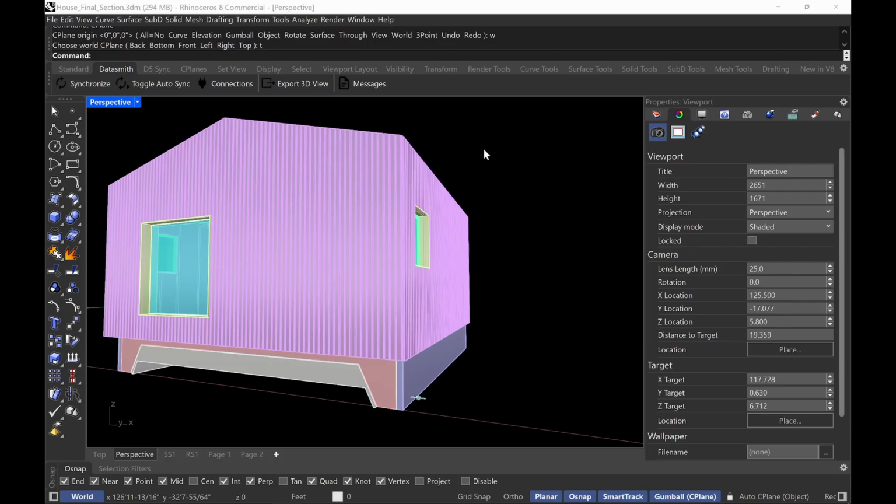And so whether you're doing a plan or a section or axonometric from a 3D model, you don't want to over model or under model. You just want to put in the amount of detail where you're actually going to be cutting your plan or your section or your axon. And then you can fix a lot of things up quite quickly, actually, in the drawing space or the 2D space. And you only want to model what you will see. When you work with sections, I would say they're more forgiving than plans because you're only seeing a very specific moment of the architectural space, whereas a plan, you're seeing a lot of other architectural elements at the same time.